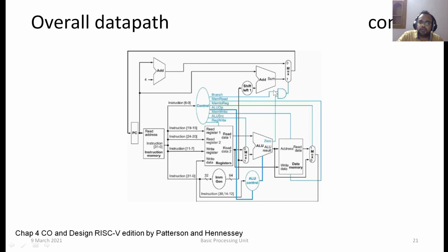And the adder you see here either picks the offset given from the branch, sorry, here it is slightly different, but the operation is the same. It would pick PC or the offset given from the instruction, etc. Slight change, but the operation is still the same.